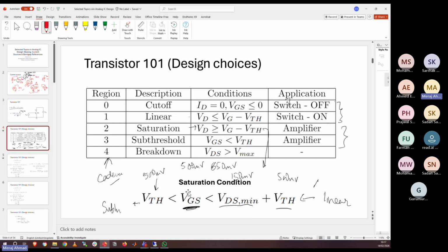So this was just how in Cadence you can start with just your VGS. Anything greater than VTH will work, and it will work in saturation and you can get a current. But the next question is, is 550 enough or is 600 better? Can anyone comment, if you want to design a current source, which VGS value should you keep?